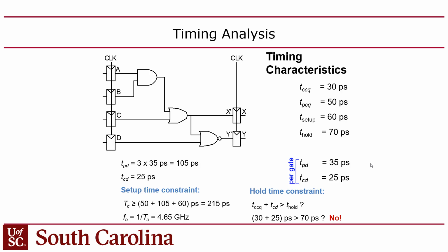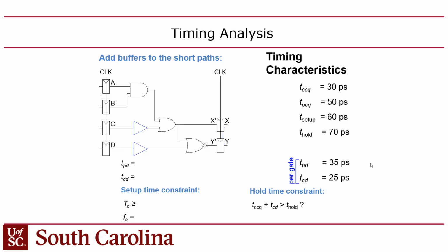So now you might say, wait a second, but what about the clock? Can't we just adjust the clock to fix that? No, because the clock is not even part of the hold time. We don't care. The clock period is not a factor in the hold time. That's only the propagation time, or the setup time constraint. The hold time constraint, we don't care about the clock. So what do we do about that? Well, pretty easy. The CAD tool would have to insert redundant buffers.